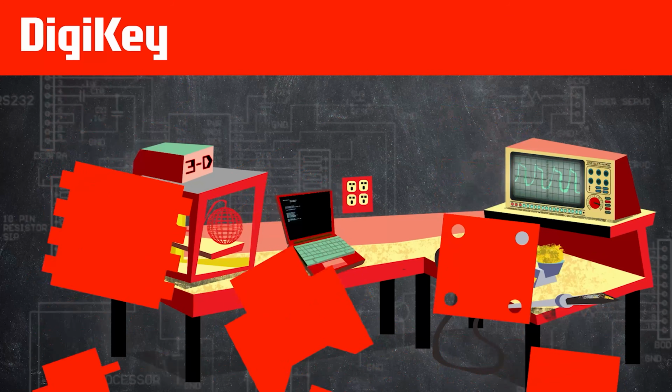For the rest of the series, I'll switch back to using the UART port on the dev kit, but feel free to upload programs to the USB port instead. Just remember that you'll need to change the overlay files to make the USB port the console going forward, just like you did in the challenge. My hope is that at this point, you have a decent understanding of the device tree, drivers, and debugging. I consider those to be the fundamental skills needed to actually start developing in Zephyr. With that, we can start looking at various applications over the next few episodes, starting with multi-threading. Good luck and stay tuned.